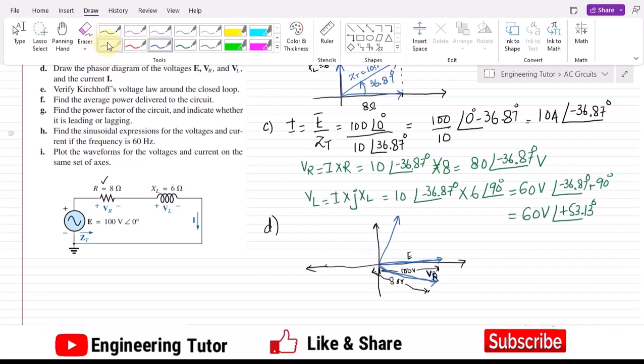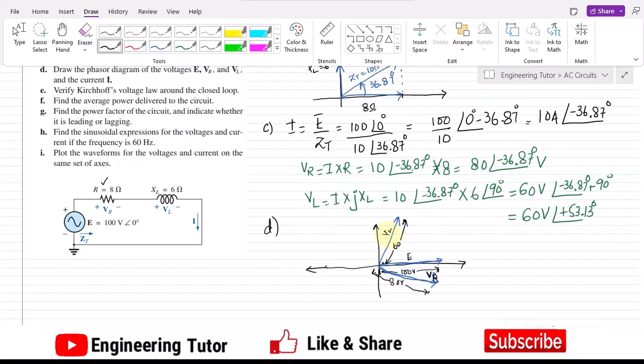The magnitude it has is 60 volts, and this is V of L. The angle it is making with this is positive 53.13, and the angle VR is making is minus 36.87. So that's why VL and VR are 90 degrees apart from each other.